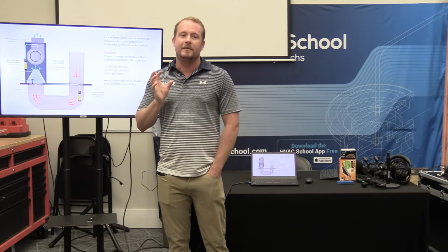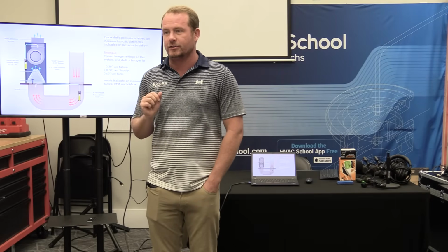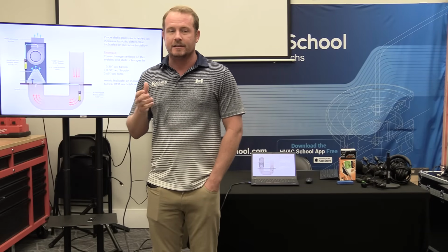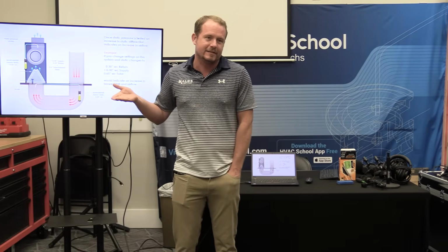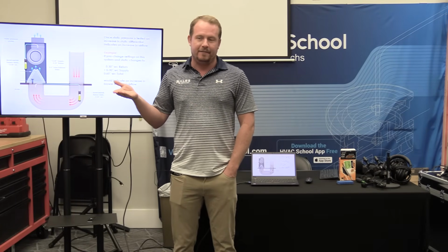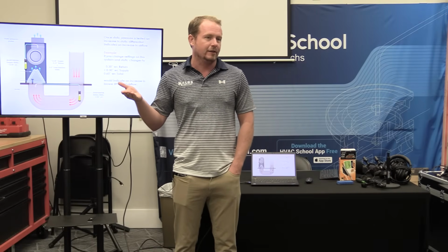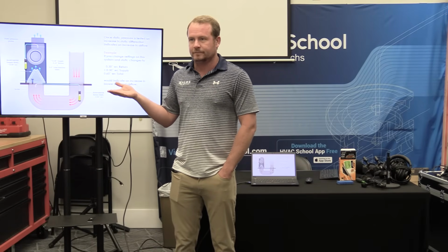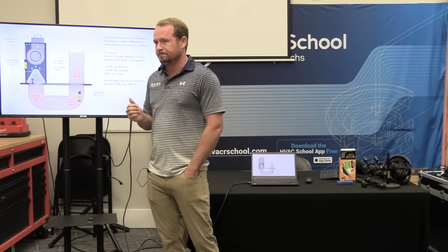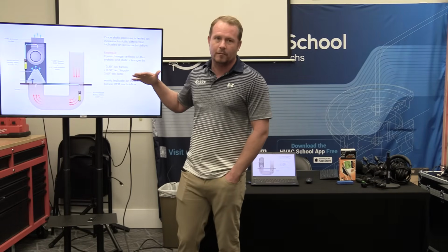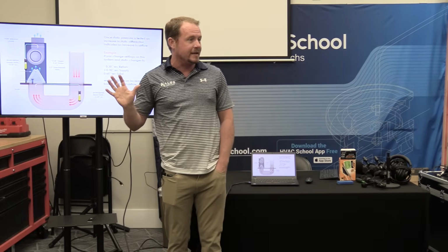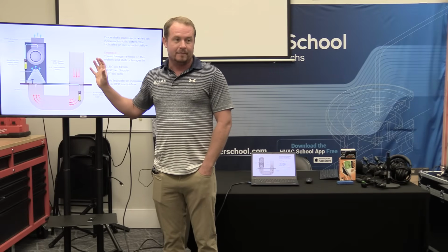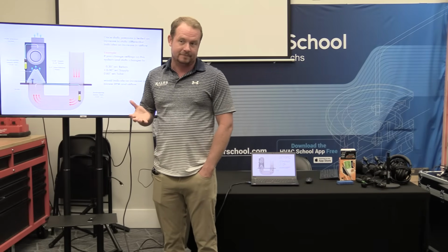It would be like saying, I checked refrigerant flow on the system when you check the pressures, right? Because you know that when you hook up to a system, you've got pressure there even when the system is off. So does the fact that you have pressure tell you that you have flow? No, in the case of an AC system. So the point is that this is not a flow measurement, this is a pressure measurement, and if everything else is the way it's supposed to be, then it means something. But if it's not, then it doesn't.